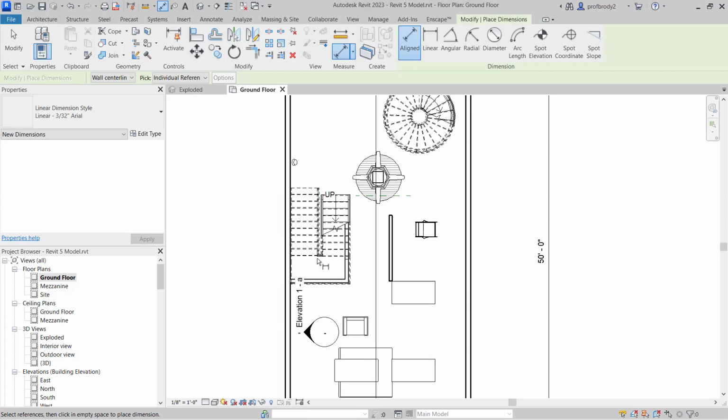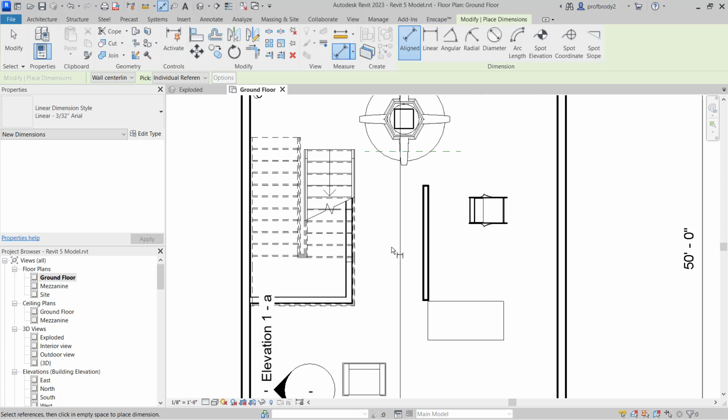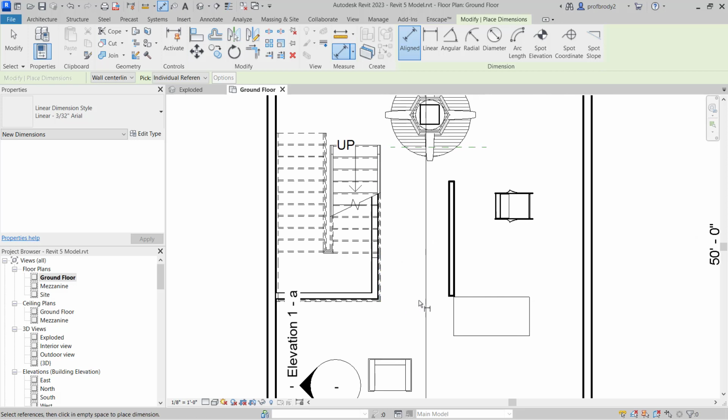We haven't been too picky here about indicating which walls are existing, which is typically the exterior walls, and which ones are new. But let's just pretend that these outer walls are existing walls, and this new one is a new interior partition. You would measure that interior partition from its center line. That's how they lay it out. But the existing exterior walls, you'd measure from the faces. If you think about it, you can't get a tape measure on the inside of a wall that's already built. You just click on the dimension tool and then click on the surfaces that you want to measure. Click in the middle somewhere where there's nothing to dimension, and it should place the dimension.